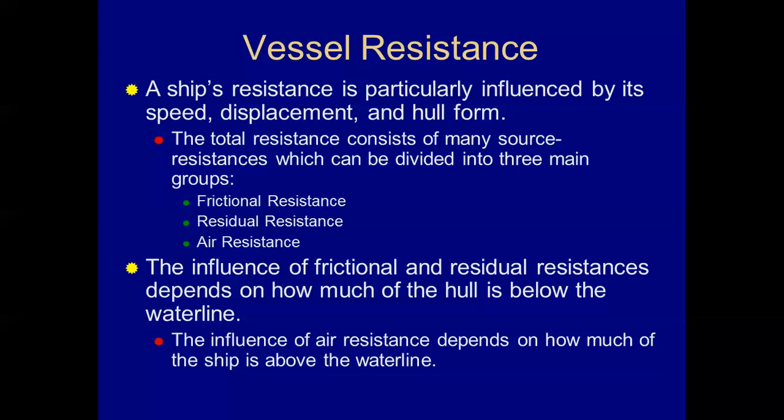So the main thing I want you to understand is that as you go into a storm, and the hull has a lot of growth on it, that will increase the resistance. To get to a certain RPM, the engine will have to develop more torque on the prop, and that will put more load on the engine.